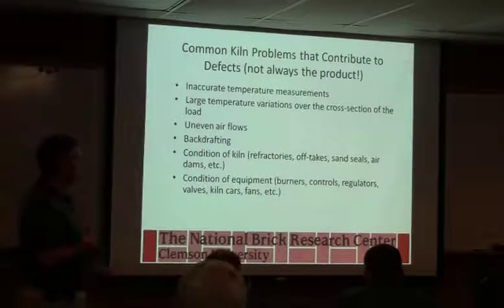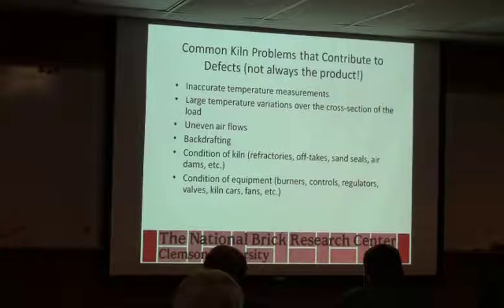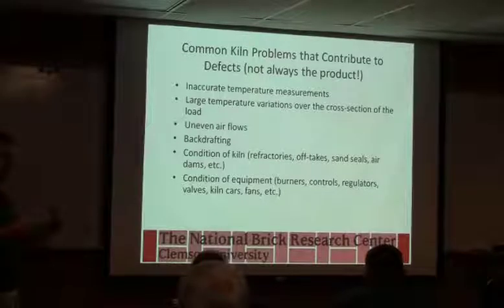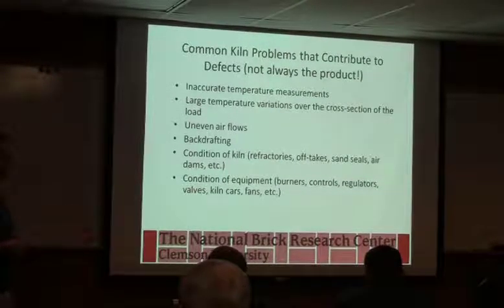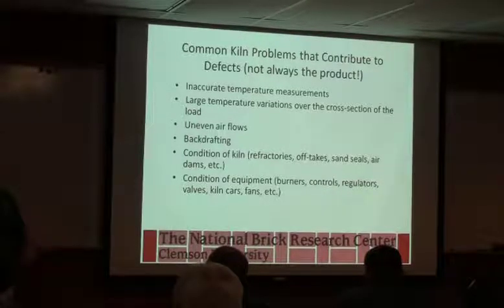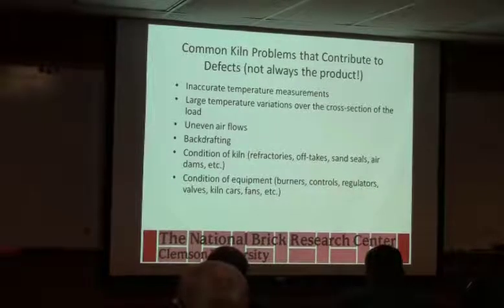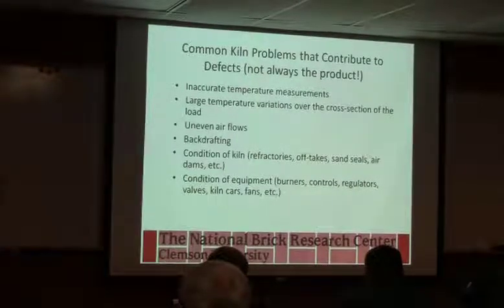Condition of equipment, the burners, the controls, how well they're actually controlling the mixture, and whether some parts you could be reducing around the product, or the excess air is off and you're cooling different areas. Again, you guys have kiln experience with producing a cool flame, you're familiar with that, where you're putting in oxygen, and if your burner supports a lot of excess air, on our Swindell kiln we can go to like 40,000% excess air, and we keep the oxygen going steady and we just vary the gas.